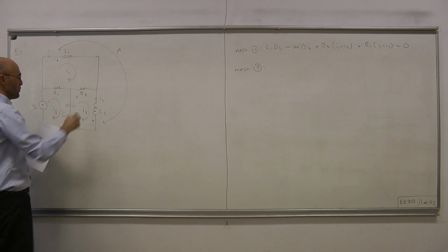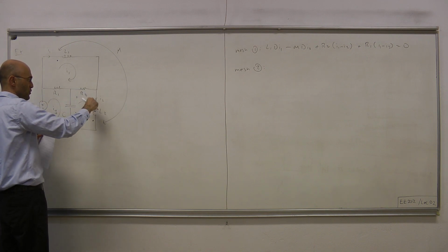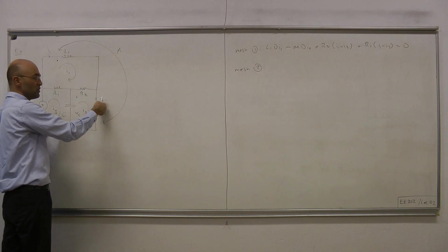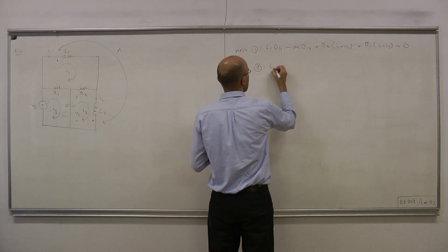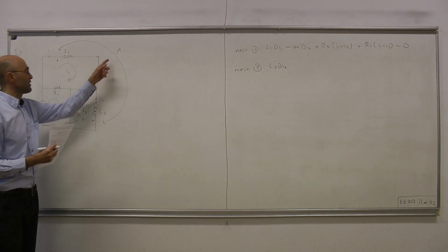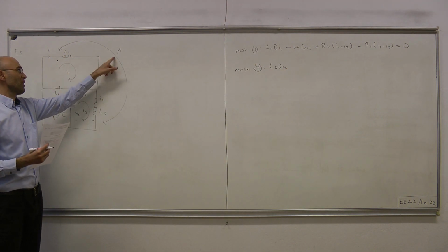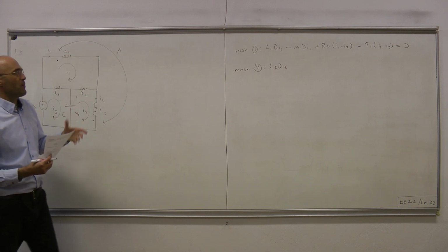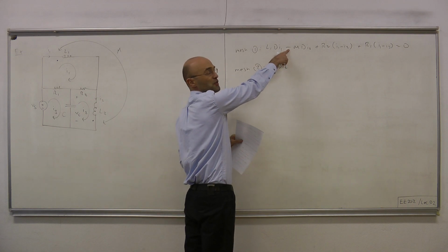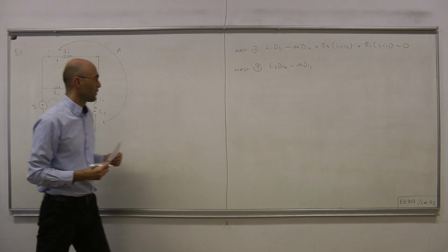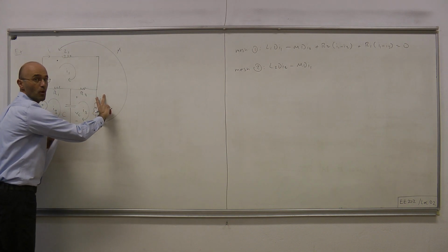Suppose that we start from this point. So this is our first voltage, plus minus. Let's call it V2. What's V2? V2 is L2 dI2. Then we have the coupling term, which is plus minus M times dI1, and we have already determined the sign, so we have minus M dI1. So it's this voltage, plus minus.